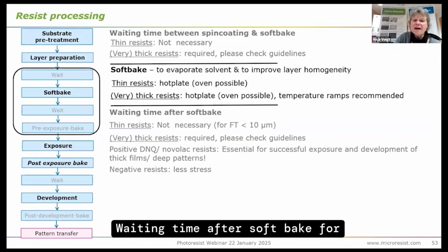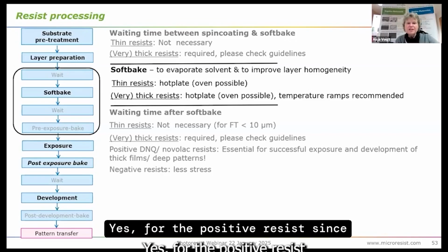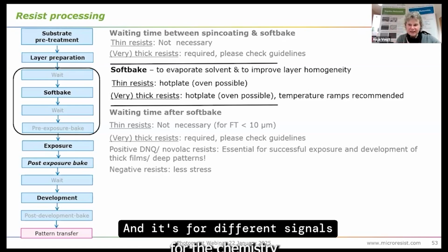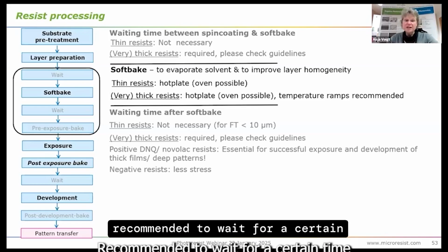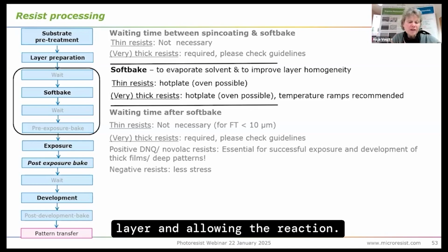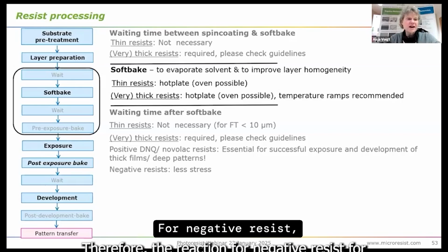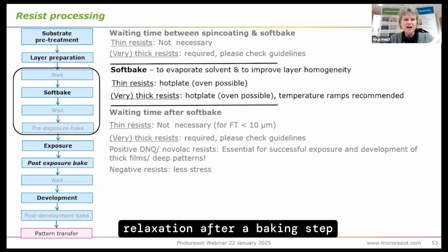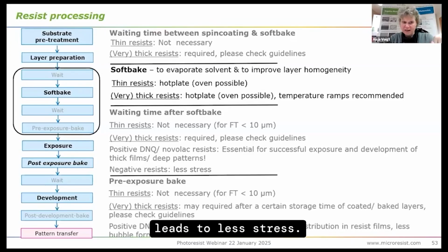Waiting time after soft bake. For thin resist, it's not required, not necessary. For thick resist, yes, for the positive resist, since they need the water for the chemistry. And for different thicknesses it is recommended to wait for a certain time so that the water can go into the layer, allowing the reaction. For negative resist, especially the epoxy resin-based, relaxation after a baking step leads to less stress.